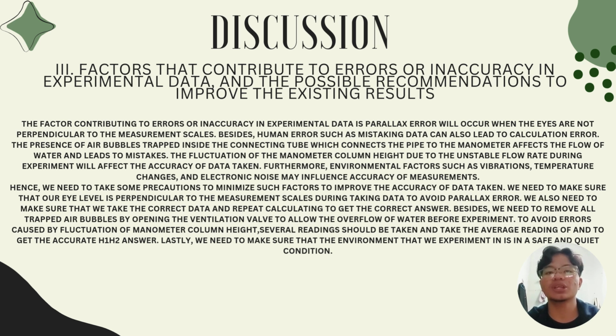Besides, we need to remove all trapped air bubbles by opening the ventilation valve to allow the overflow of water before the experiment. To avoid errors caused by fluctuation of the manometer column head, several readings should be taken and averaged to get accurate HL, H1, H2 answers. Lastly, we need to make sure that the environment in which we experiment is safe and quiet.